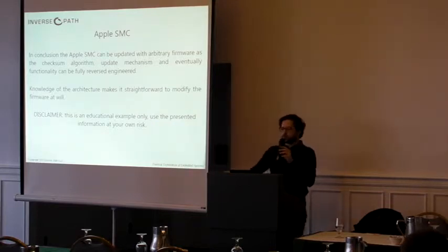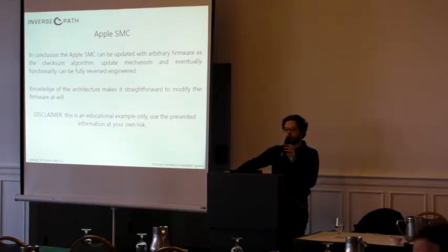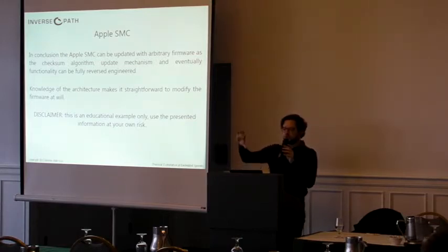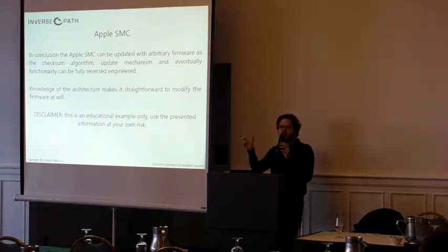So there are some tools that will automate the process of checking known CRC algorithms on your image, because one other thing that you have to figure out is what's the actual firmware space that the algorithm is computed against. Because if you have a header that you don't know is a header which is not part of the checksum, then every time you try your checksum, it will fail.